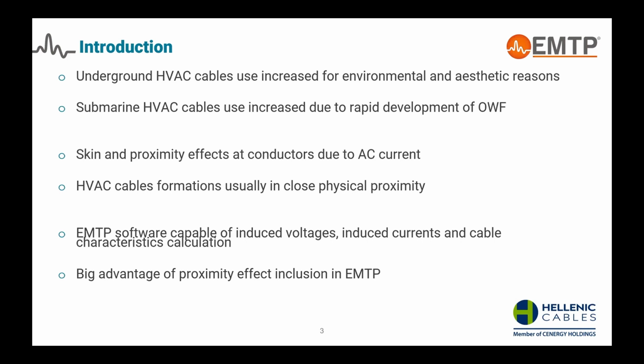In both of them, due to AC current, skin and proximity effects at conductors are developed. The high voltage AC cables are usually in close physical proximity, many times because of space limitations, mostly in underground installations, or because of technical reasons like reduced induced voltages or induced currents. The EMTP software is capable of calculating these induced voltages, induced currents, and other cable characteristics. And a big advantage against other software is the inclusion of proximity effect in the latest version 4.2.